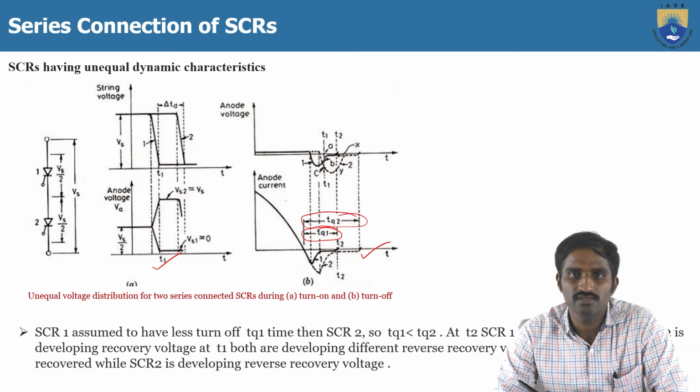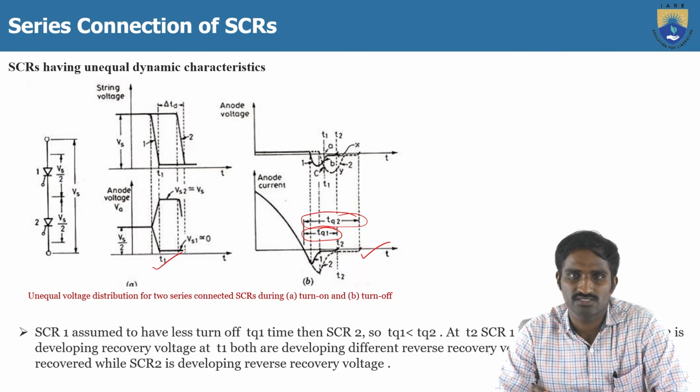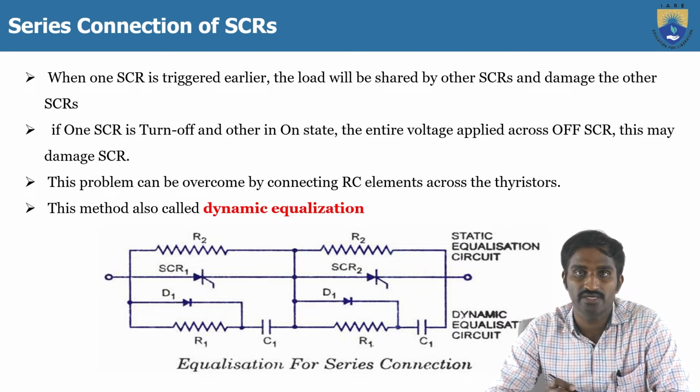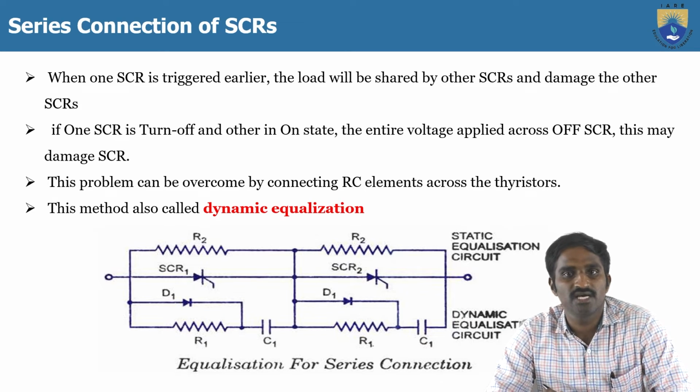So because of the different reverse recovery times, the turn off time is not the same in both cases. So when one SCR is triggered earlier, then the load will be shared by the other SCR, and it may damage the other SCR.